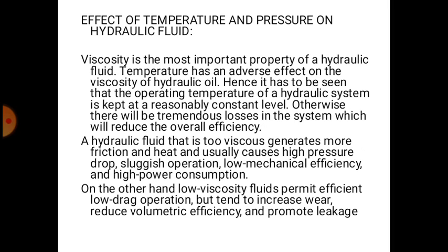So now we will discuss the effect of temperature and pressure on hydraulic fluid. Viscosity is the most important property of the hydraulic fluid. Temperature has an adverse effect on the viscosity of hydraulic oil. Hence, it has to be seen that the operating temperature of a hydraulic system is kept at a reasonably constant level. Otherwise, there will be tremendous losses in the system, which will reduce the overall efficiency.